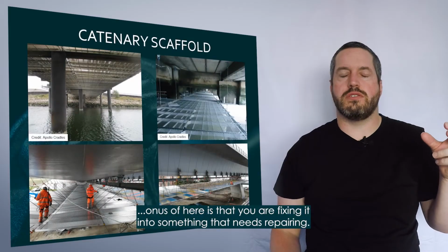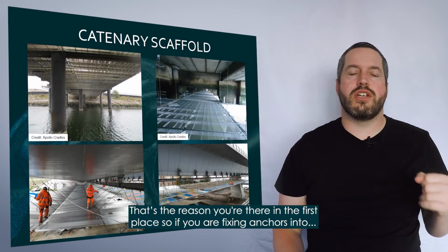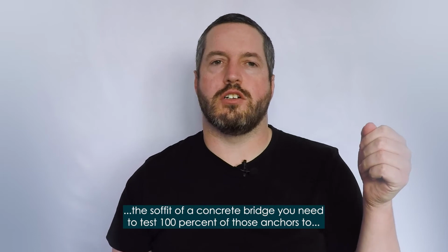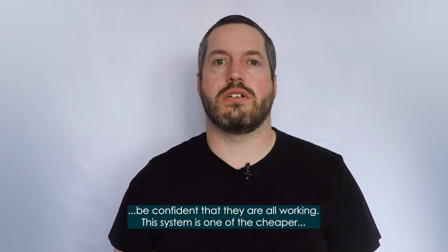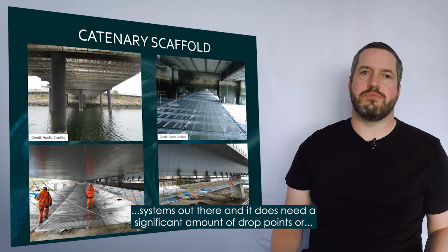What you need to take onus of here is that you are fixing into something that needs repairing. That's the reason you're there in the first place. So if you are fixing anchors into the soffit of a concrete bridge, you need to test 100% of those anchors to be confident that they are all working. This system is one of the cheaper systems out there.